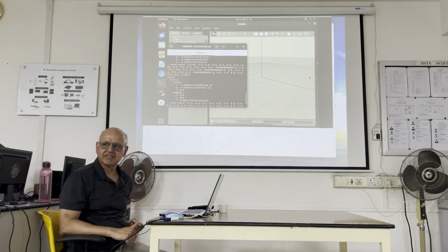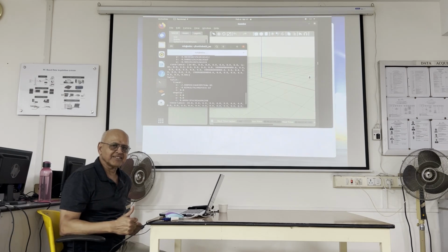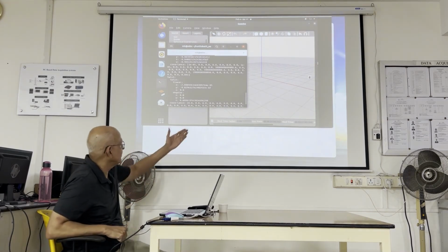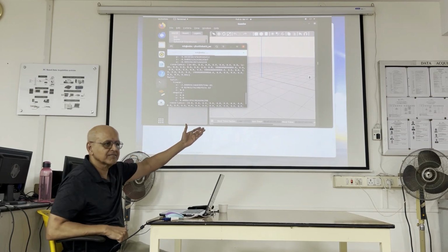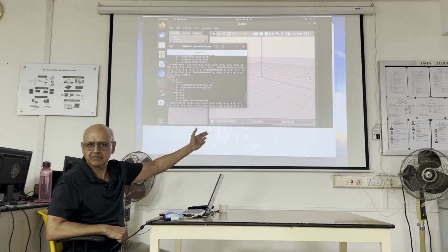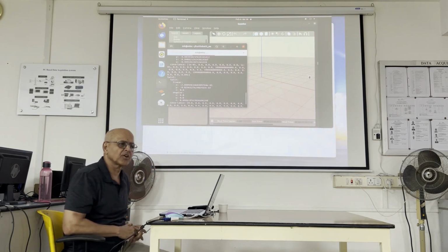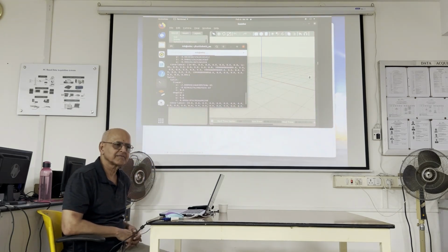Then we stopped it. We ran the echo program, rostopic echo ODOM, again, and we compared with where we think the robot is. So it's like we close the loop and we understand what ODOM is doing. That's it. Is it okay?